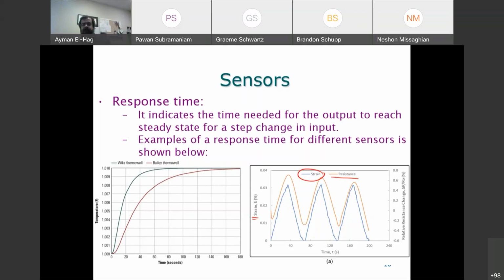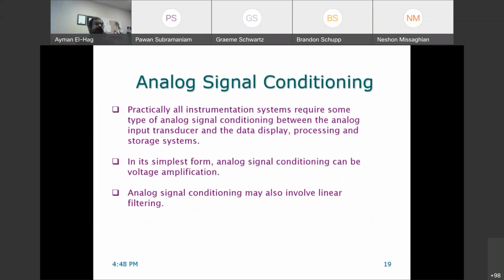I want to measure temperature. I'm bringing my sensor from an ambient temperature, which is 22, 23 degrees centigrade. And I have boiling water. And I put the sensor in and immediately take a temperature. No, you have to wait until you see that the readings are coming closer, or following this curve, until it reaches the steady state and you don't see much variation in the measurement. Then you can take your measurement. Now, as I said, some sensors do that very fast. Some take their time to do that.